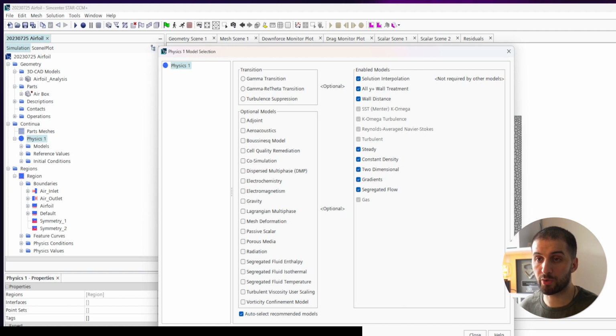It's very important to accurately model the boundary layer behavior, especially for airfoil simulations, as it significantly influences lift and drag and all these parameters that we'll have a look at in the post-processing stage. For this reason, we've chosen K omega as a best practice. But again, it really depends on your use case. If you go from an airfoil to, let's say, a backward facing step, the turbulence model might be a completely different one. It depends on the physics that you're trying to solve.